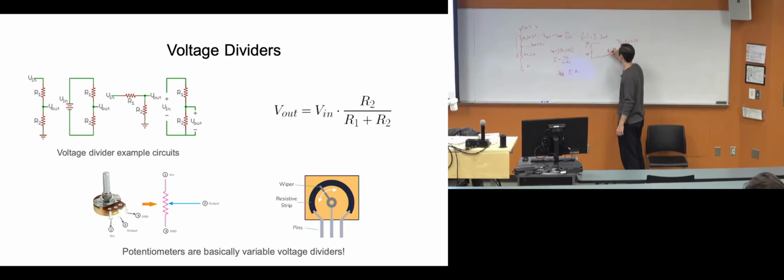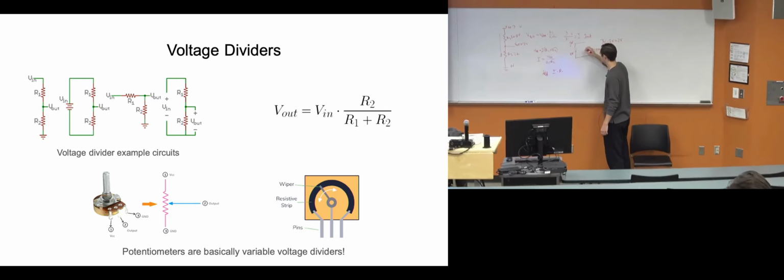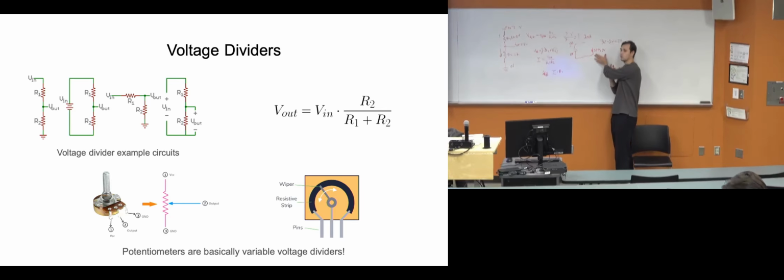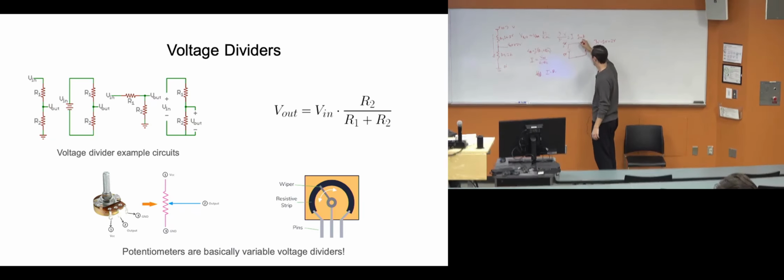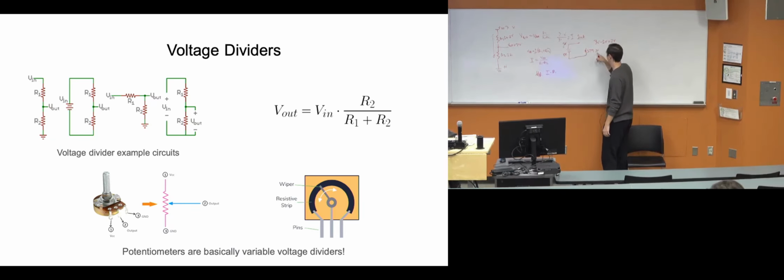But let's say this is your STM. This needs, we'll just say 3 volts. It's really, they take 5 and then go down. But for this example, let's say it needs 3 volts, right? We could use a voltage divider to get down to these 3 volts. So we need to drop 2 volts and save 3 volts, right?